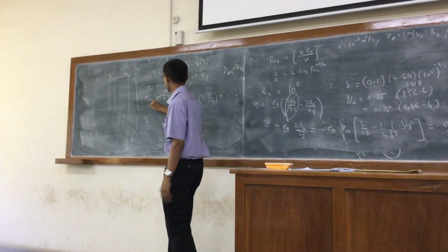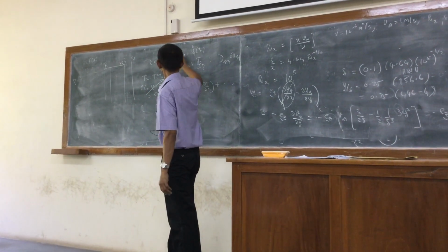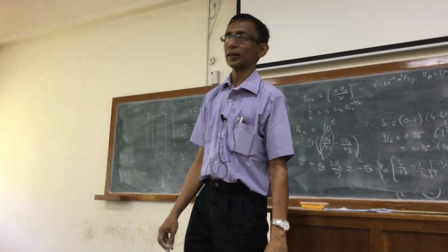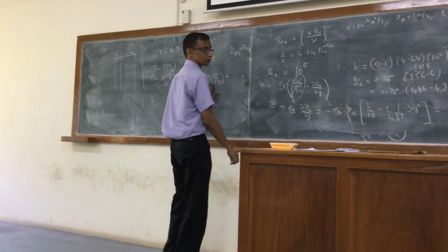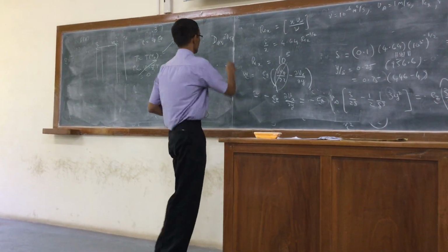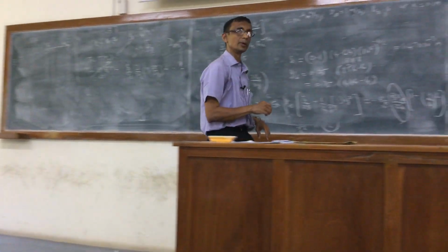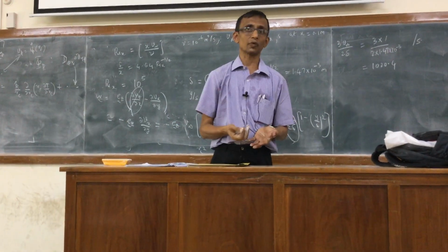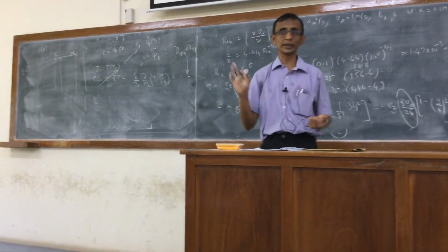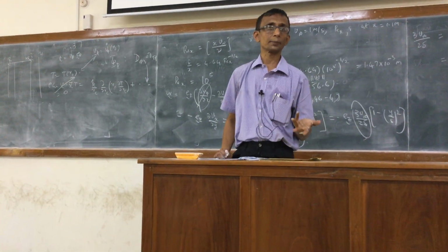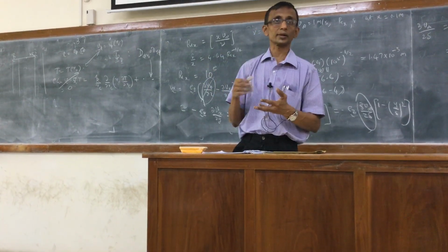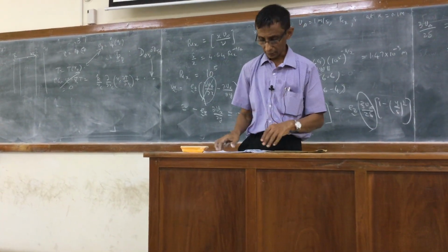You can verify that this is equal to 0 for these two conditions. That's why it is 0. And then you neglect the axial conduction term here, as we have always done for a long cylinder. Then you have to calculate the viscous dissipation term, and then simple integration would be straightforward, because this would be a function of r alone. Right? So you can easily integrate the equation and get the temperature profile between the inner and the outer cylinder of the fluid. Right? So that's the problem.